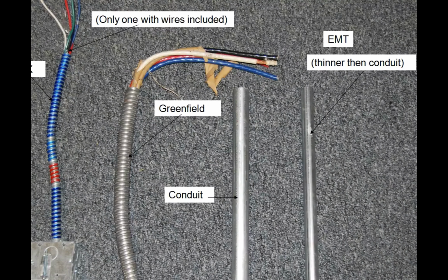Greenfield is thicker, it's bigger, and that one you run your own cable through. Whenever you buy Greenfield, these are generally used for, I've seen them in a lot of temporary uses. That way you can choose and select what's running through it. Conduit, as you can see, is almost like a steel pipe. Very rigid, strong, thick material. And then EMT to the right. It's tough to tell without looking at it through a cross section, but it's just a much thinner version of conduit.